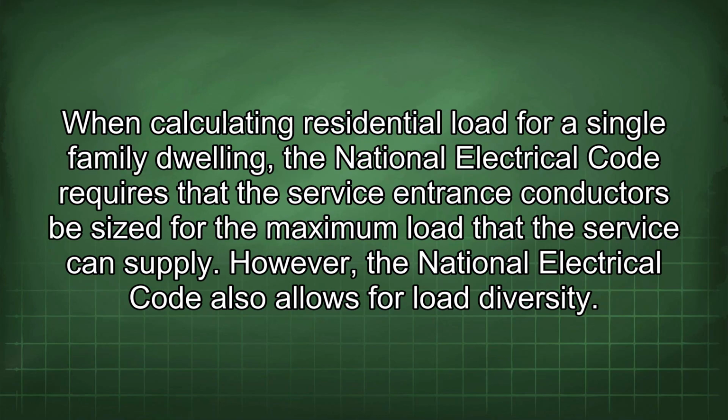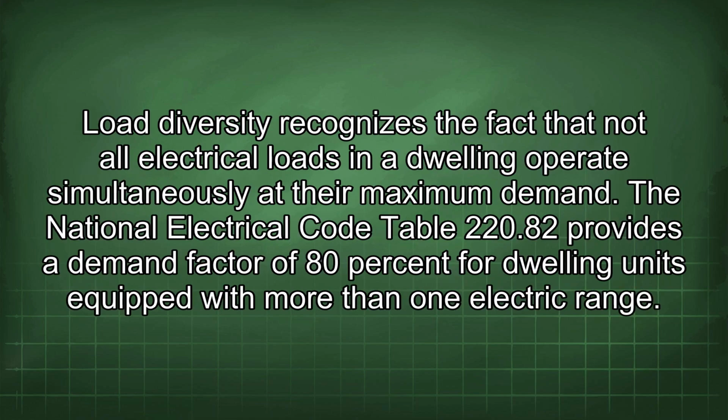When calculating residential load for a single-family dwelling, the National Electrical Code requires that the service entrance conductors be sized for the maximum load that the service can supply. However, the National Electrical Code also allows for load diversity. Load diversity recognizes the fact that not all electrical loads in a dwelling operate simultaneously at their maximum demand.